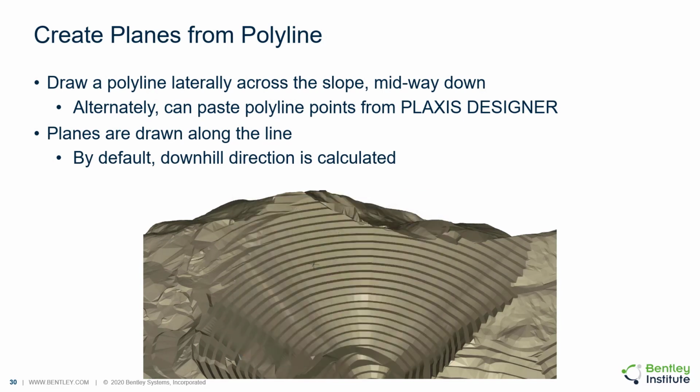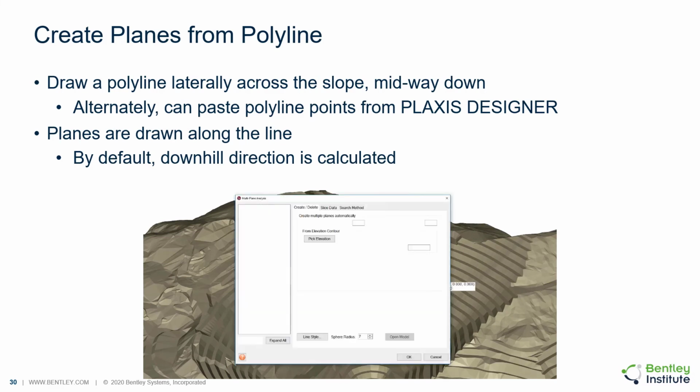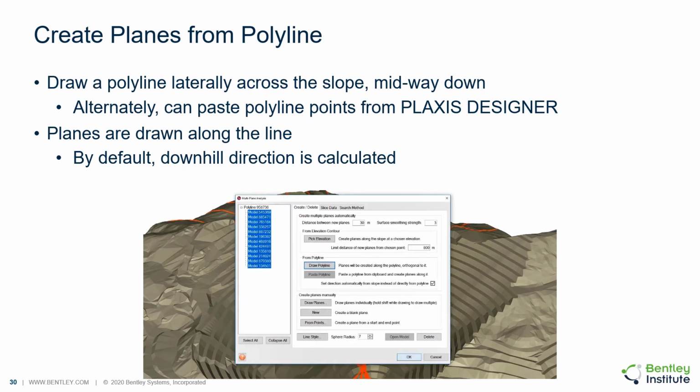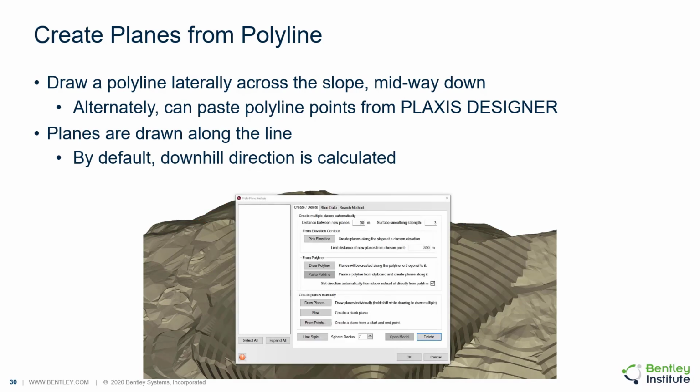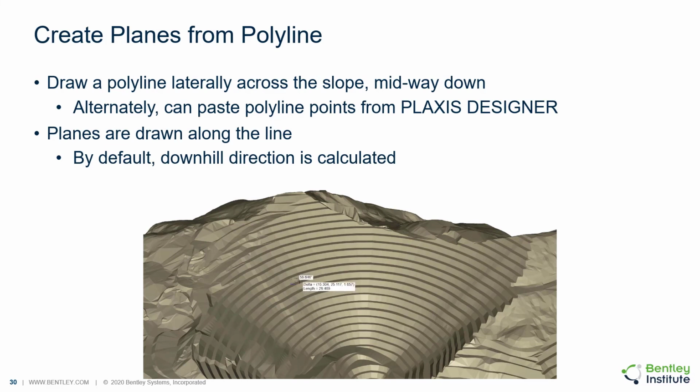The user can also create planes based on a polyline. The polyline can be drawn laterally across a three-dimensional slope and midway down the slope. Polyline points can also be pasted in from PLAXIS Designer. Planes are drawn along the line in the most downhill direction.